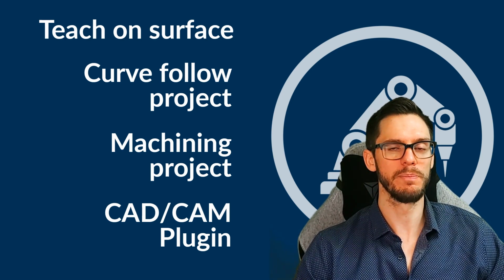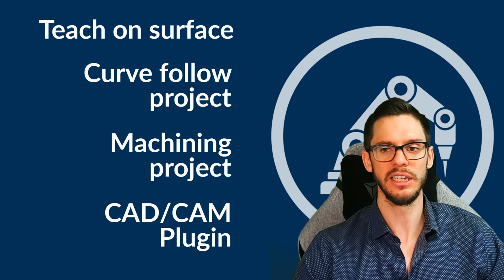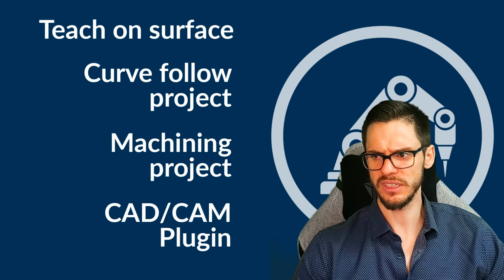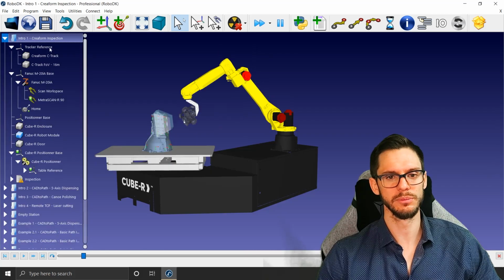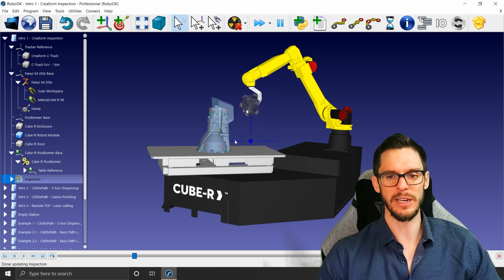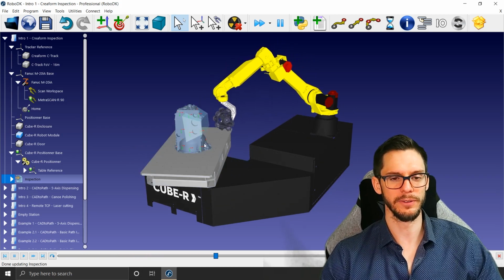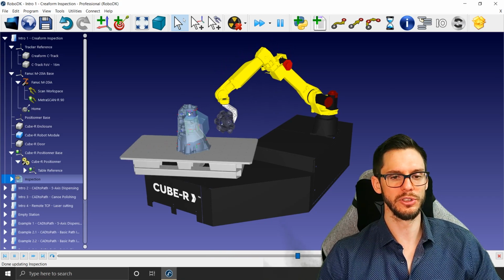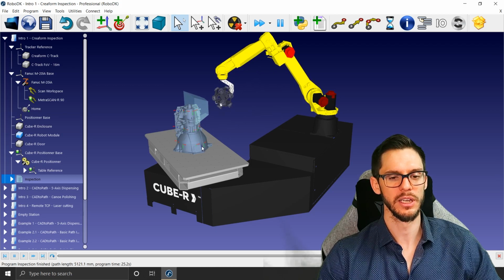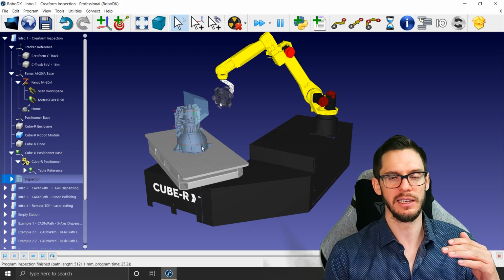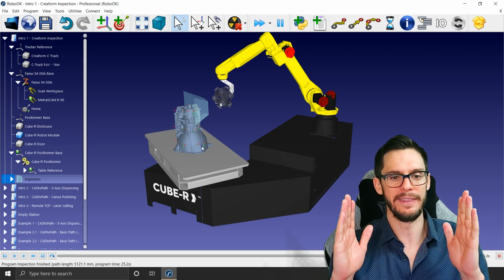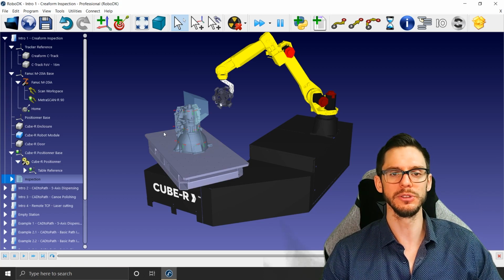In the first webinar, we generally concentrated on the teach on surface, which gave us this example here. I can run this program. This is an inspection project that we did in the first webinar. Super useful. You just click directly on the surface to create your targets, or your points to reach. You're sure that you're always in the same orientation, either always normal, and you know that you are always at the same distance from the part. So this is super useful.